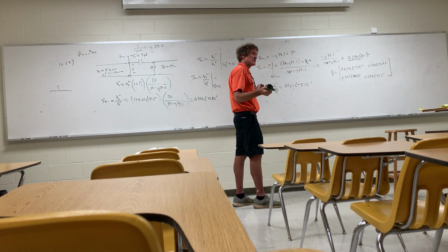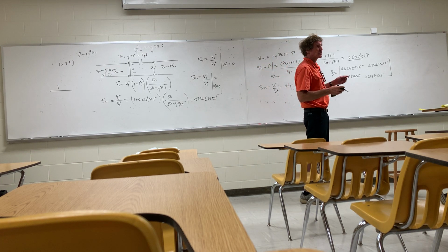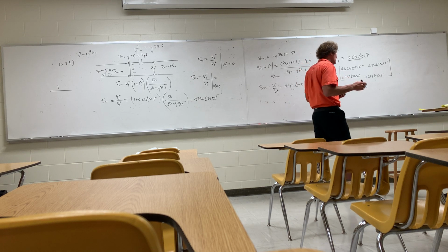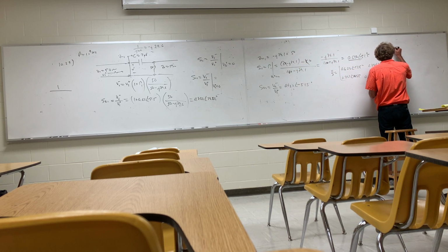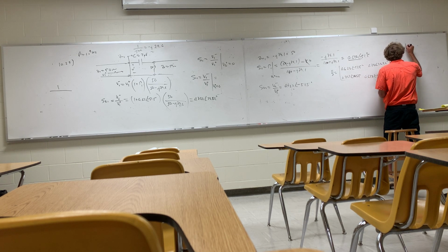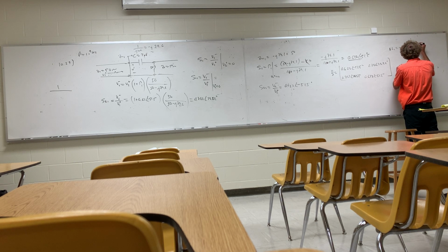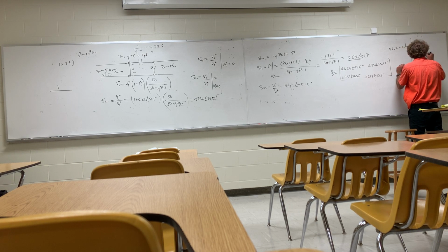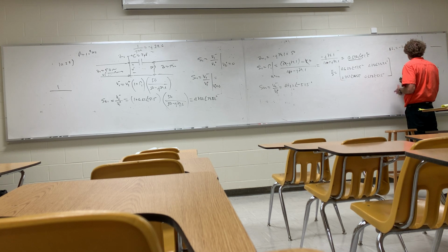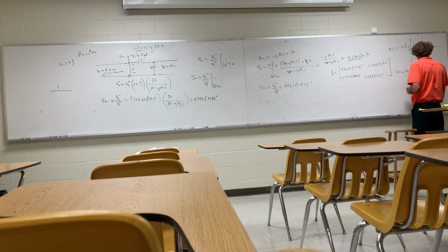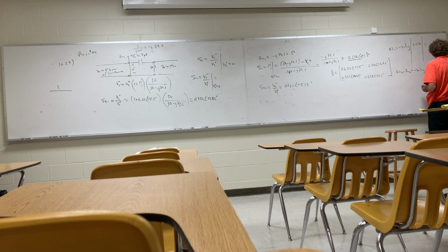Now I'm going to get the return loss and the insertion loss. The return loss on port 2 is going to be the return loss at port 1 because it's a reciprocal network. So the return loss on port 1 or 2, I'll just say on port 1, is minus 20 times the log of the absolute value of S11, so 0.623. Can you tell me that? Anybody? 4.11. 4.11? Yes, and that would be in dB.